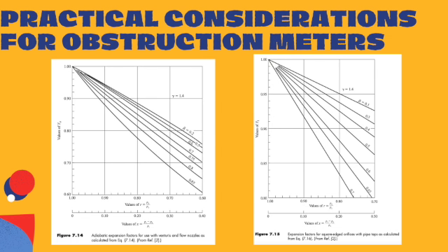It's supposed to be the various flow coefficients are plotted as a function of Reynolds number, and it's defined as Re equals the fluid density times mean flow velocity times diameter at the particular section for which the Reynolds number is specified, divided by dynamic viscosity.